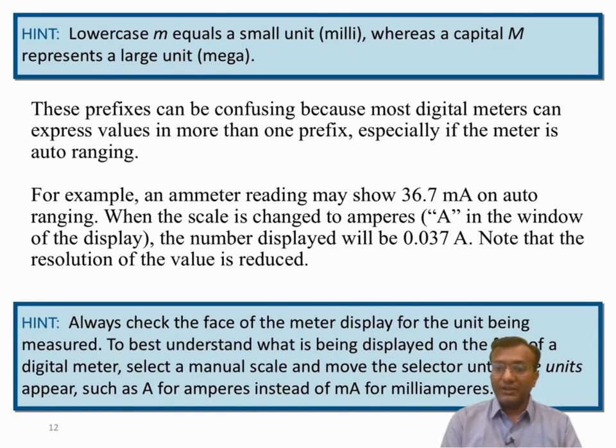So, winding up today's lecture, coming to the summary, we have seen how to measure the resistance of different components in a circuit using a multimeter. Measuring this resistance is essential for troubleshooting and confirming circuit integrity. Using an ohm meter effectively, understanding readings, and knowing how to handle prefixes all contribute to accurate and safe electrical diagnostics. I hope you have understood today's lecture.